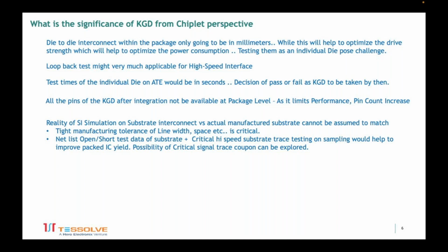If that will impact the cost because the substrate gets damaged or something, then we could choose a critical signal for worst and best case within that package and replicate it as a small coupon, like we do in the PCB.